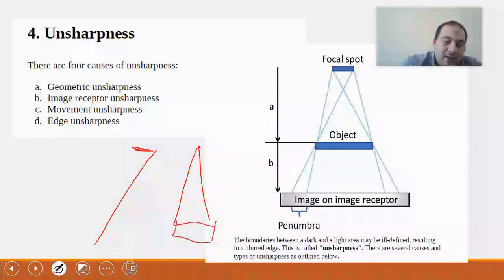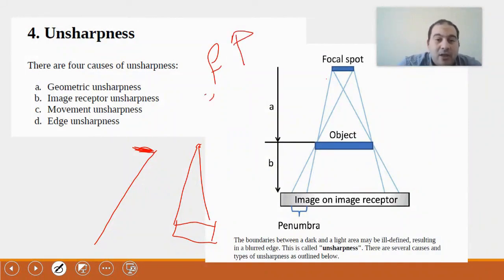Regarding your device, it will come from a very small object size, but if your device increases in size, this will cause your penumbra, because the same image will be exposed to part of it, while another part is exposed differently. Therefore, this is what will cause the issue with the penumbra. So, the larger you make it, its size increases as the geometric unsharpness or penumbra increases.